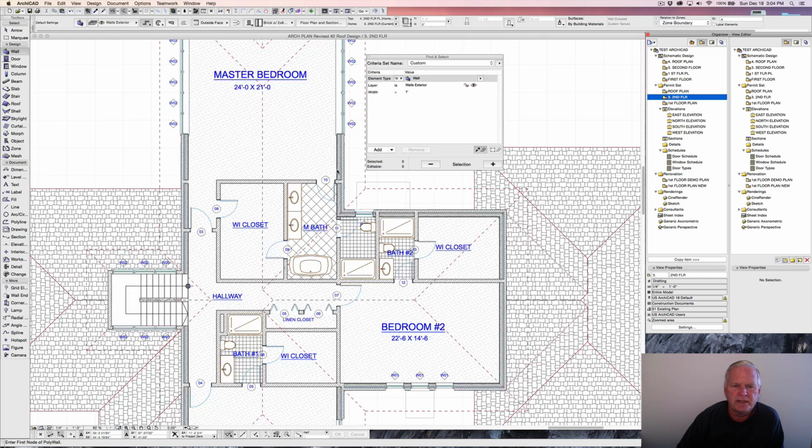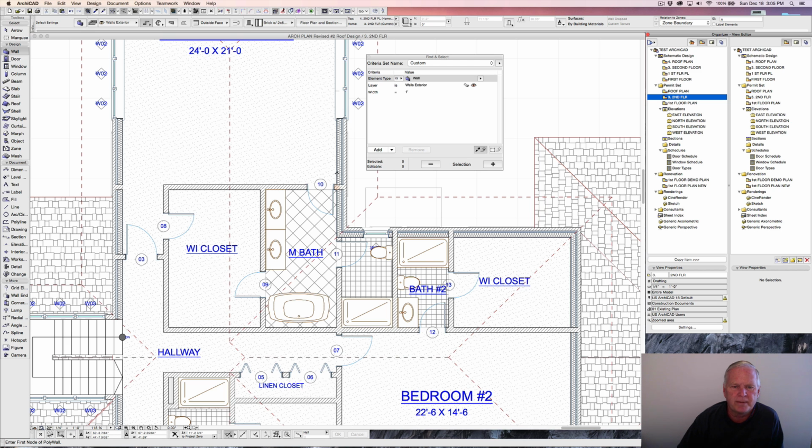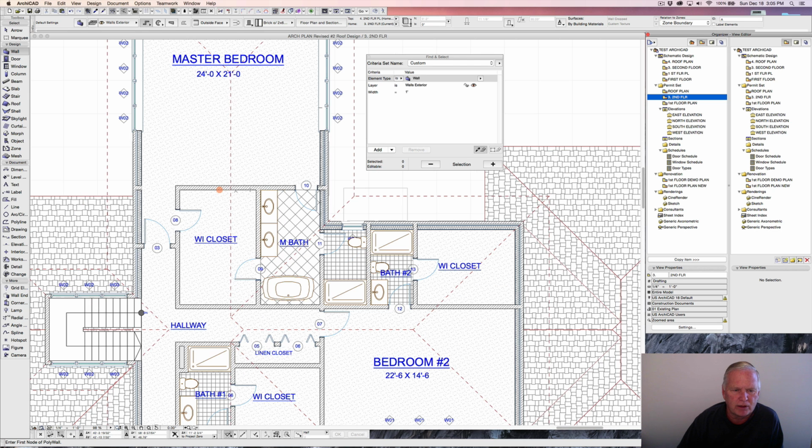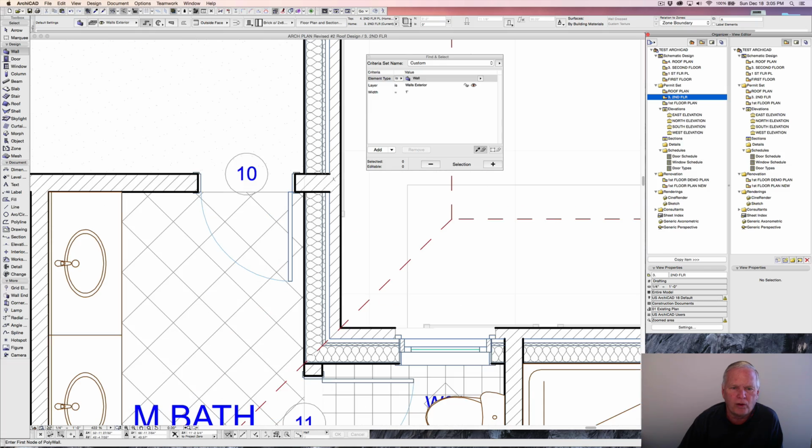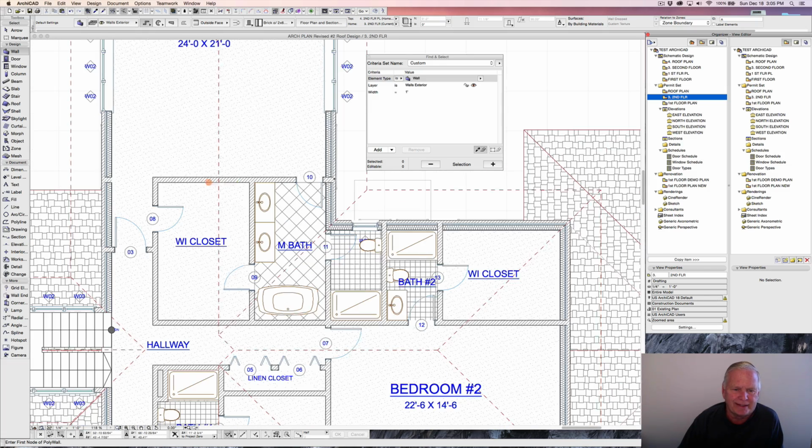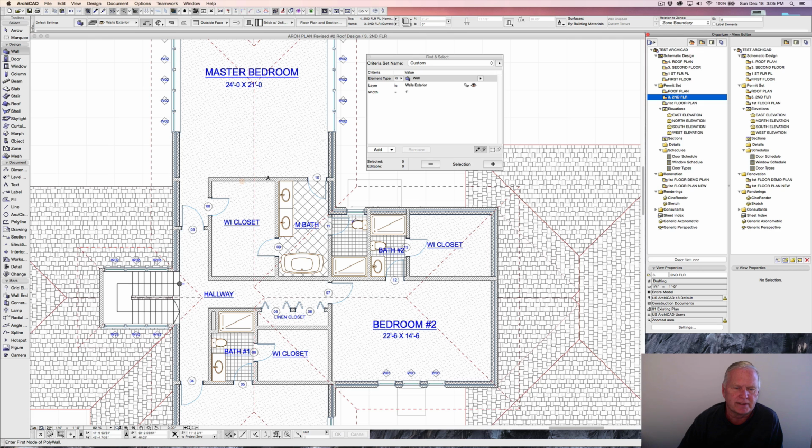And as you can see, it's set all those nicely, but what it isn't doing quite correctly, because all our interior walls are set for brick right now, is it's melding the brick wall into this exterior. The easiest way to fix that is just go ahead and set our interior walls to the correct thing. So we'll go find all of those. They're wall instead of exterior.